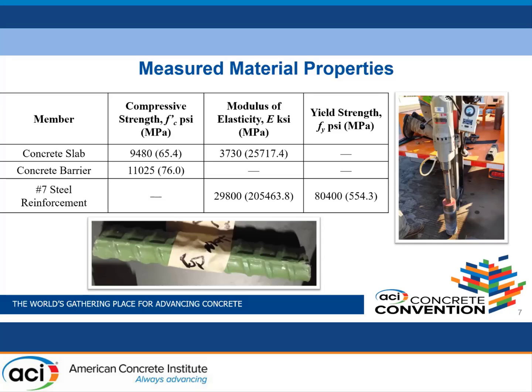However, the modulus of elasticity that we measured from the bridge deck was 3,730 KSI, which actually correlates to a concrete compressive strength of about 4,000 PSI.